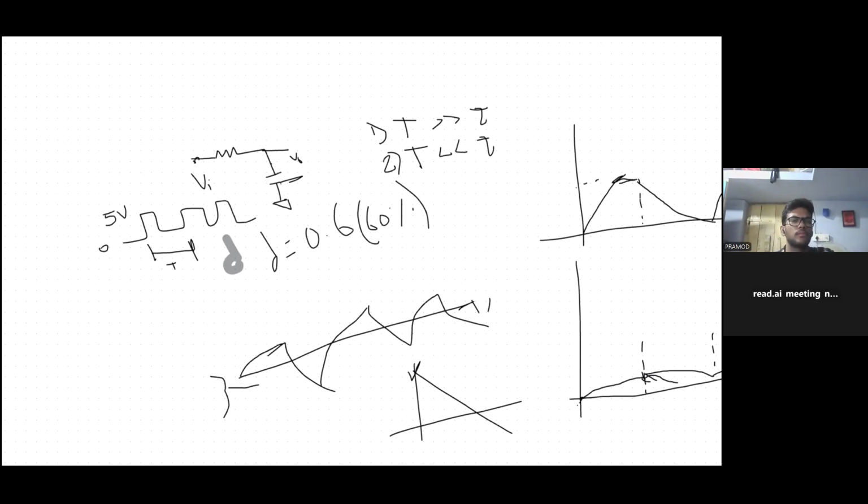Yeah, I think you are very near now. That is also a correct answer actually. So when we say a system is in steady state, let's say the output is achieving steady state, at that time charging and discharging rates are same, meaning whatever charges are flowing into the capacitor and whatever charges are going out of the capacitor will definitely be same. So then the average current will become zero. That is correct actually, because whatever charging, whatever discharging, it is same for the capacitor.